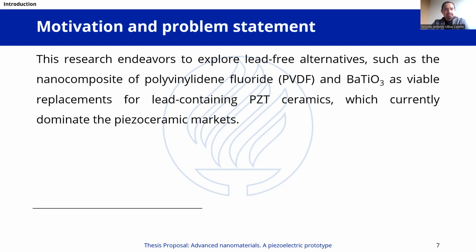Also, another parameter, which I mentioned in this discovery by Roberts studying barium titanate, is polarization by applying an electric field during the synthesis of these piezoelectric ceramics, and also the way we synthesize them, as I mentioned, spin coating or force spinning.